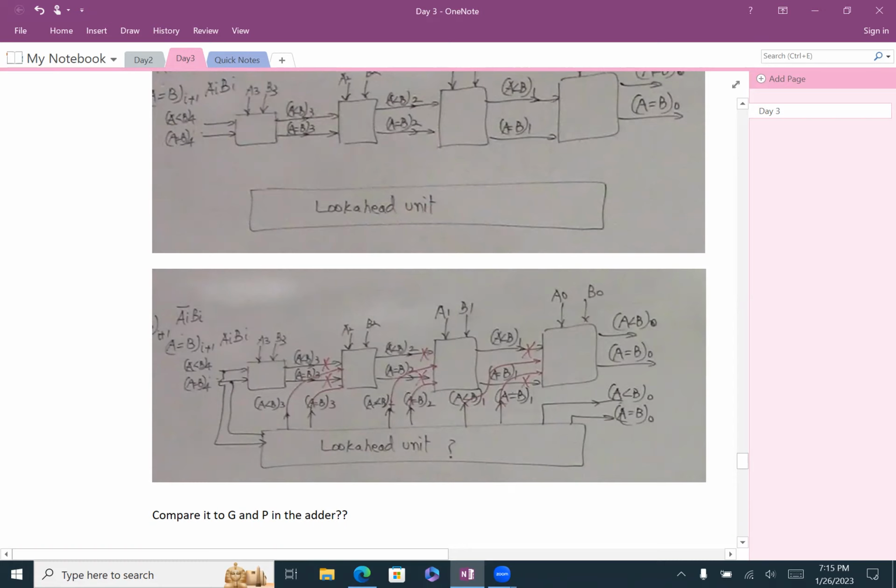It's complicated. I know it's a lot of information. Actually, it's not a lot of information. It's a lot of steps, but it's the same concept. All right. I'm sure if you go review it again, you will understand the trick of how to find the P and G's, then how to find the super block. And after that it will be really simple. Even if I give you any circuit, you build the 4-bit block, then based on that, you start building and make it bigger, bigger, bigger. From 4, 16, 64 to, that's enough. If you want to do 256, that's fine, but there's no need.